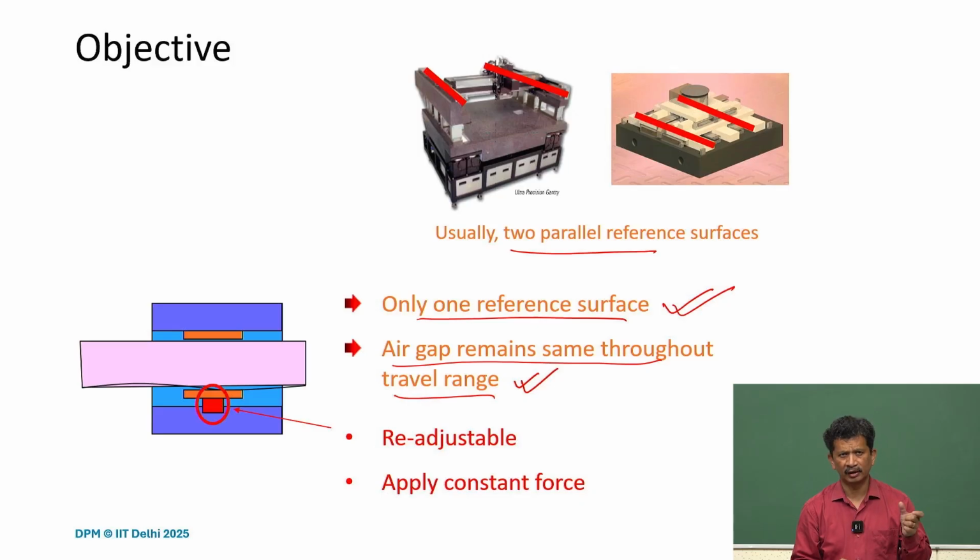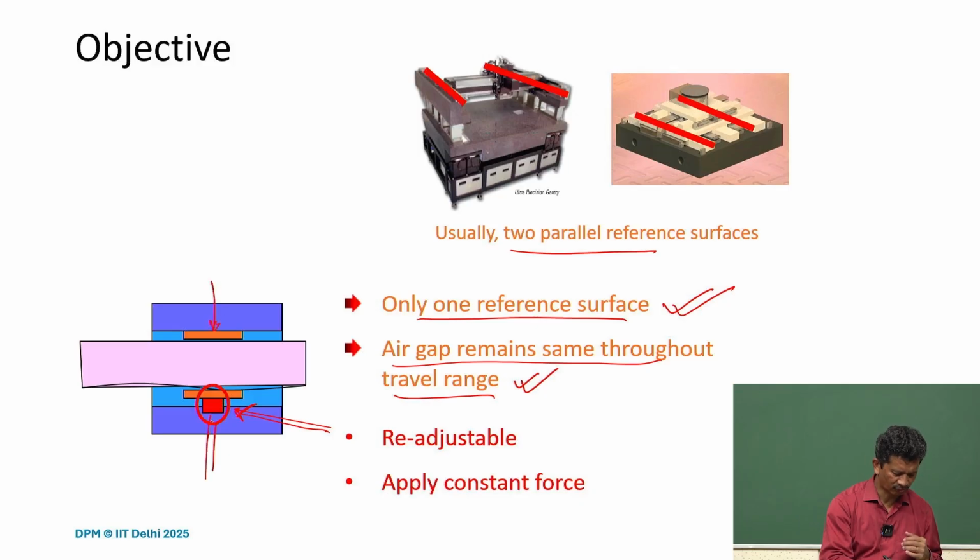Any error which is local can be compensated, because if it's repeatable, then we know where it is and what the error is. So we can achieve repeatability. But how do we achieve that air gap? Assuming there is some kind of magic here, and a block, we put an air bearing, and then another opposing air bearing, co-located, to get the required preloading.